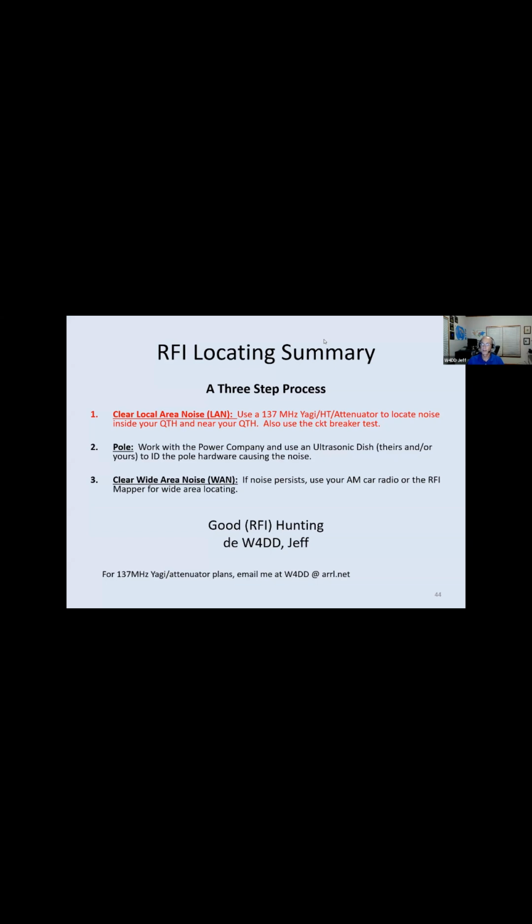And the infrared pictures I've seen of units so far, there are 2 things that I had some doubts about. One is they show heat, which is good, but current passing through wires and joints generates heat. So the images I saw were kind of vague as to where the problem was. Yeah, there were some hot spots, but were they really issues?